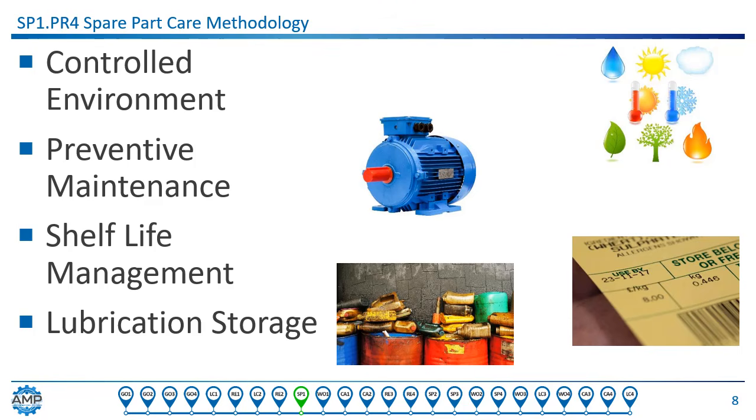Any spare parts that do require special storage conditions, like a controlled environment, should be stored together. And storage of spare parts should be done under storage conditions that follow manufacturer's recommendations. The storage orientation should be considered for any spare parts requiring maintenance, like rotating the shafts on motors. The shaft should be accessible for maintenance. All spare parts must be stored according to the principles of shelf life. Use-by dates should be managed through the store's procedures and the CMMS.